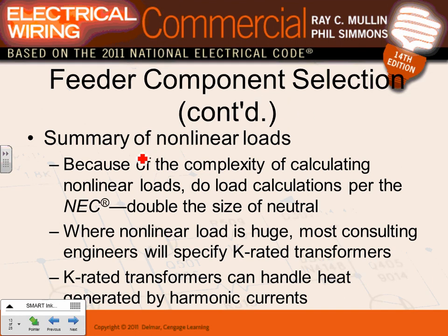So nonlinear load, a little bit about the nonlinear load I'll show you guys. When you have nonlinear load, here's my point, it could double the size of your neutral. So instead of phase A, phase B, phase C adding up to 0, they add up to double the amount in one phase. How do they do that? I will spare you the math behind that. By design, they just don't add up. The reason why phase A, B, and C add up to 0, guys, is because we designed it to do so, and we put linear load on it.